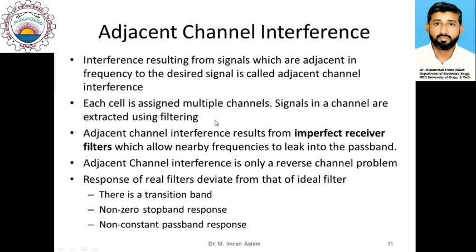But the important thing is that filtering is a non-ideal process. The practical filters differ from the ideal response that we study from theoretical aspects, and that non-ideal response results in some frequencies being extracted by the filter which are not intended to be there.